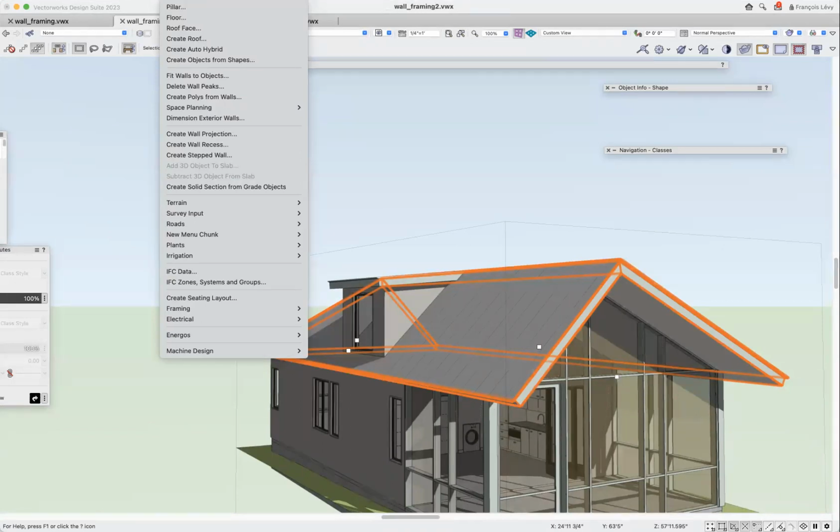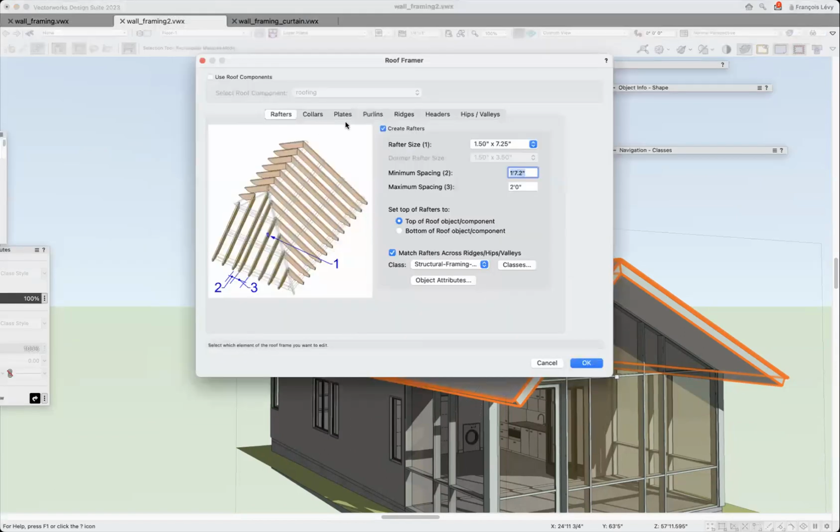So if I change the roof pitch, one of those roof pitches is at a 6/12. If I decide I want to move the ridge over and make it a 5/12, it's not going to edit the model. I just need to run the command again. So clipping out the dormer hole isn't going to have any effect. I'd have to do that manually.